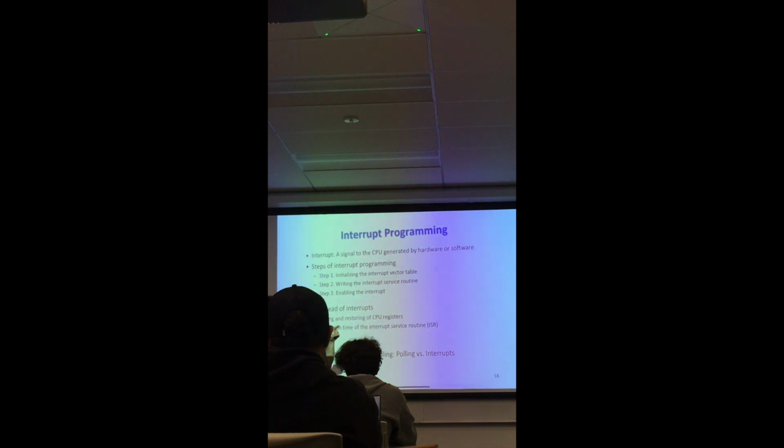Stack is located at the highest possible address, and it stores information by lowering its address: 255, 254, 253, 252, and so on. When you remove all the information from stack, it goes back. But if you store too much information on stack, it will interfere with program execution, because they are located in the same RAM, in the same address space.